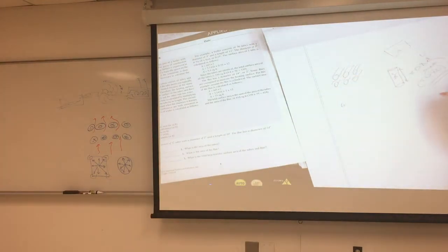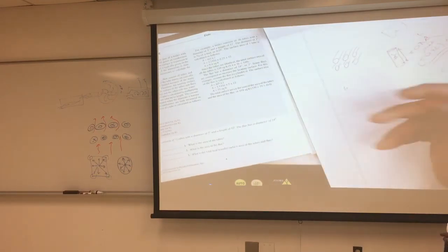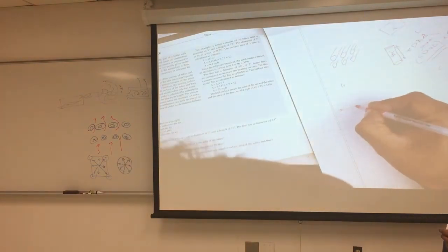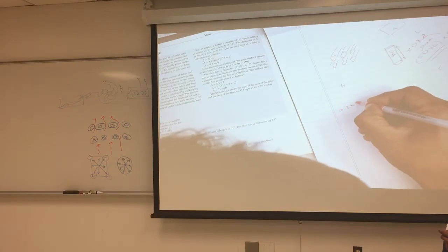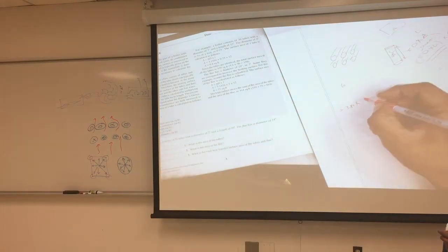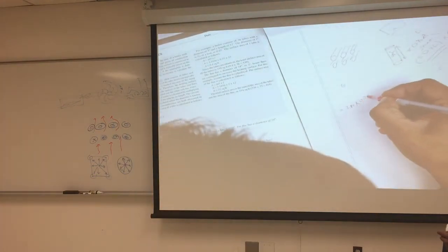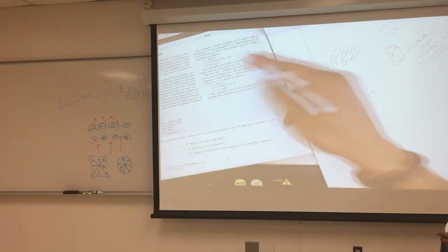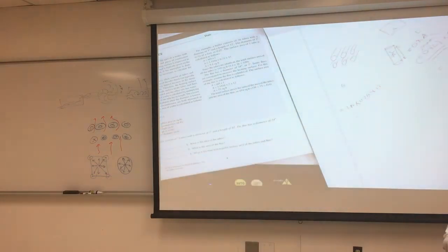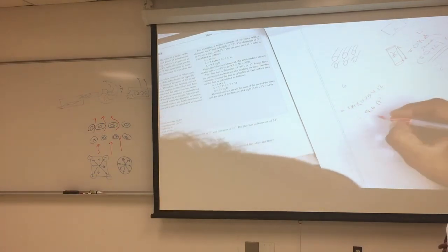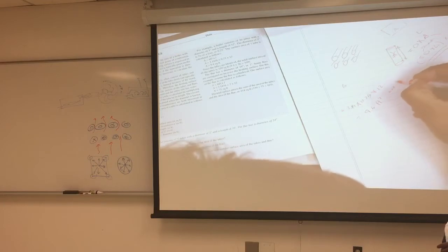So we have 6 here, and that will give you the surface area for the tubes and the heat exchange surface. So let's take this example and do the math. So pi is 3.14 times d, the diameter. I'm going to use the same diameter here, which is 0.25, times the length for each tube, which is 12. That's going to be 9.4 square feet. That's for one tube.